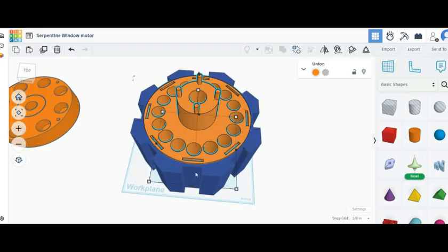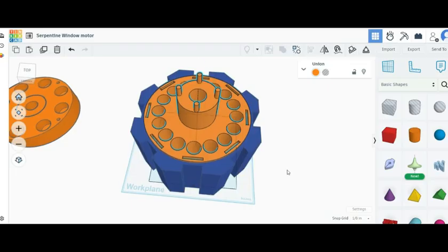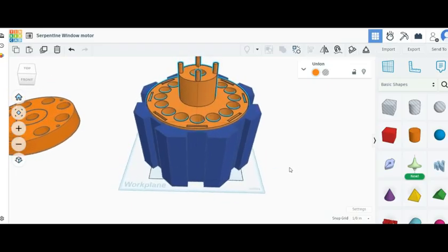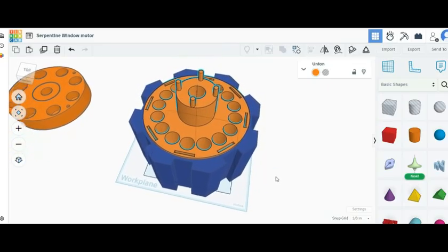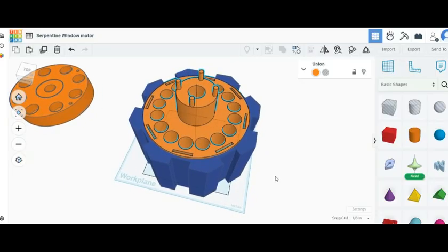And again, if it was a window motor, you would take your first one, you'd go like this, and you'd go over there. But the problem is, I've got this big honking thing there, but even without that, you still have the axle that you've got to worry about. And you just do the one wind, and then you do a second wind, and it's got to dodge the wire that you put on the first wind, and so on and so forth. It's just more complicated. This way you just zoom, zoom, zoom, zoom, and you should get the same thing. And I think it'll be a lot easier to wind and things like that. So that's where I'm going with the serpentine coil.